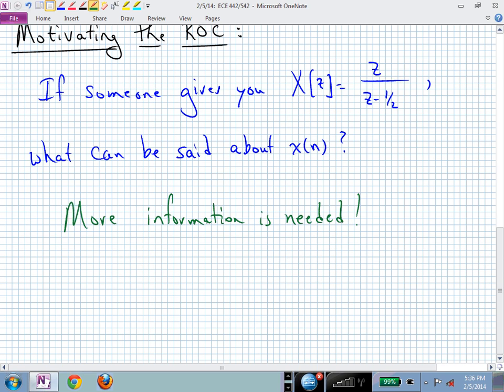You need two pieces of information in order to go backwards from a z transform. You need the transform, and you need to know the region of convergence. With those two pieces, then you can be better informed to explain or describe what the time domain waveform x of n equals. Now, why did we not need to worry about that for Laplace? Most of our Laplace discussion has always been one-sided, meaning we were always dealing with time domain waveforms for non-negative values of time t. Then we could immediately inverse Laplace transform and obtain this x of t expression.